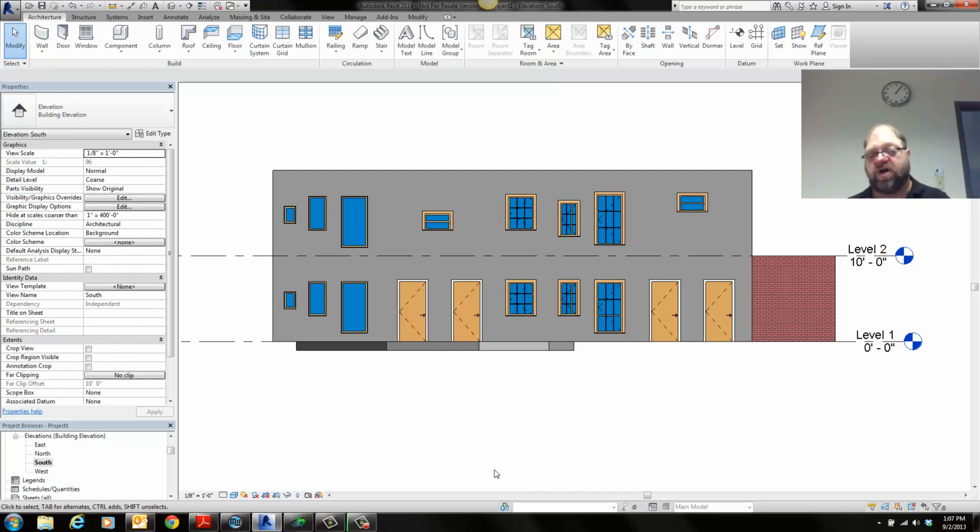have a complex relationship where a level has to exist before the item can exist, because its sill height, in the case of a window, is directly related to the level that it exists upon. So that covers at least the idea of families and parameters and how they interact with each other, and it starts to help you understand how to control the geometry of the families themselves rather than just assembling the pieces that you have.